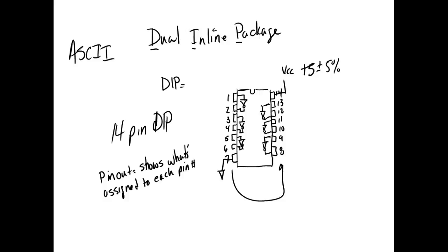So you got a 14-pin DIP, and they go in 2s. So the next one would be a 16-pin, because it's a dual in line, right? Then an 18, then a 20, a 22, 24. When they got to 24, they had to do something different. They made the package wider. But the way we set up the pin numbers is exactly the same. First of all, you identify the pin 1 side. It's either going to be a notch or a little nipple right beside pin 1. Then you start counting down, come up, and go down.